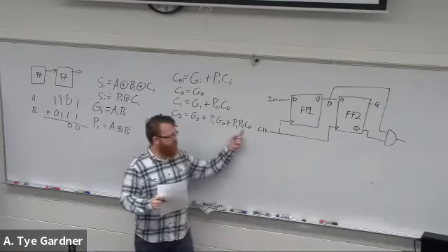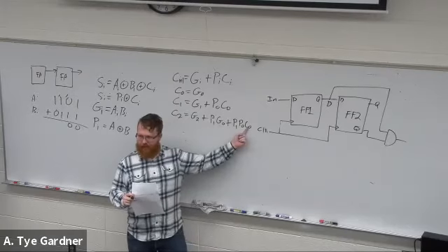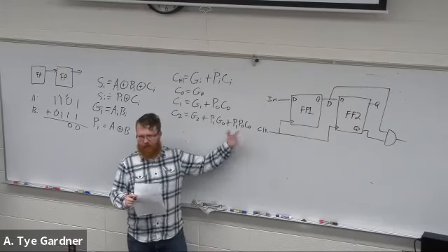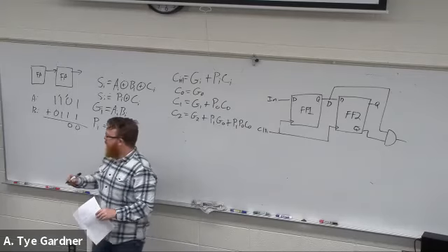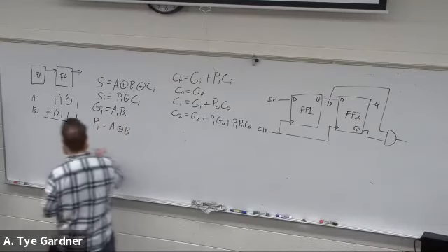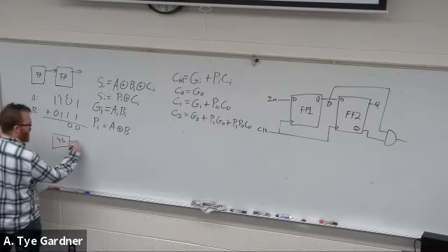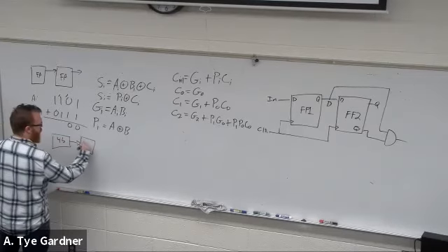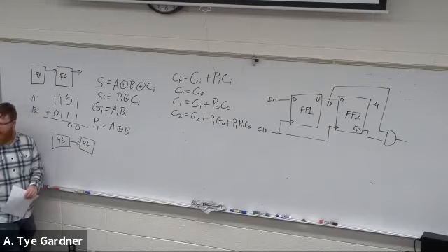So this term is only necessary if there can be a carry in, essentially, right? That's the question, is can I bring in a carry? Which we may want, right? Because we can build a system where I build a 4-bit adder and I just start stringing the 4-bit adders together.